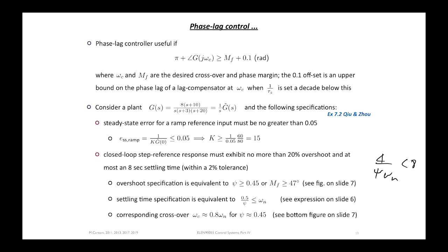All right, good morning everyone. So today we're going to continue looking at examples of controller design from the perspective of achieving desired open loop transfer function characteristics. We can think of performance specifications as relating to desired steady state behaviour, and that's all about the shape of the open loop transfer function at zero frequency.